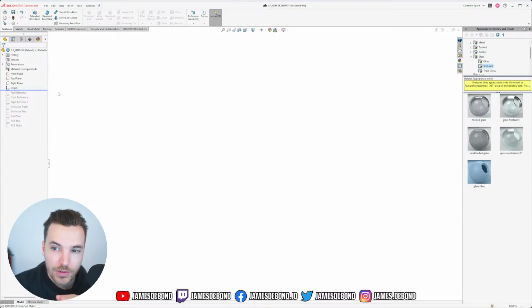Because I haven't chosen that display yet, I'm just going to make up some reference sketches for it. And I always put them at the beginning before my actual sketches, so that everything in my skeleton model can reference those other components.